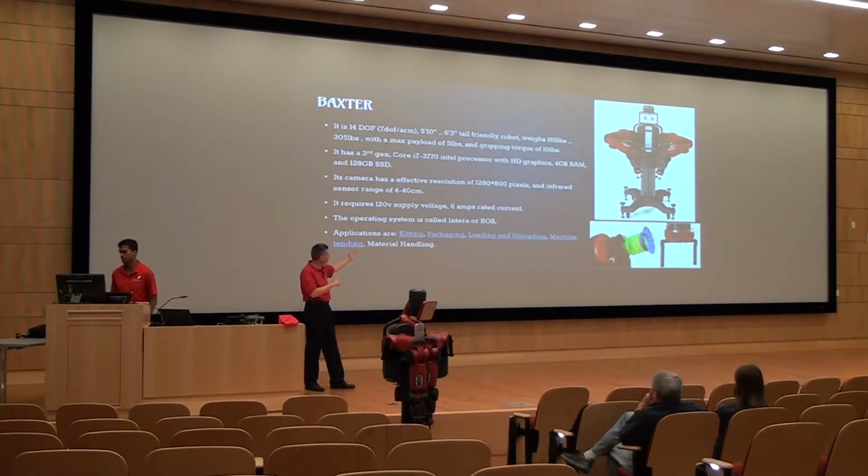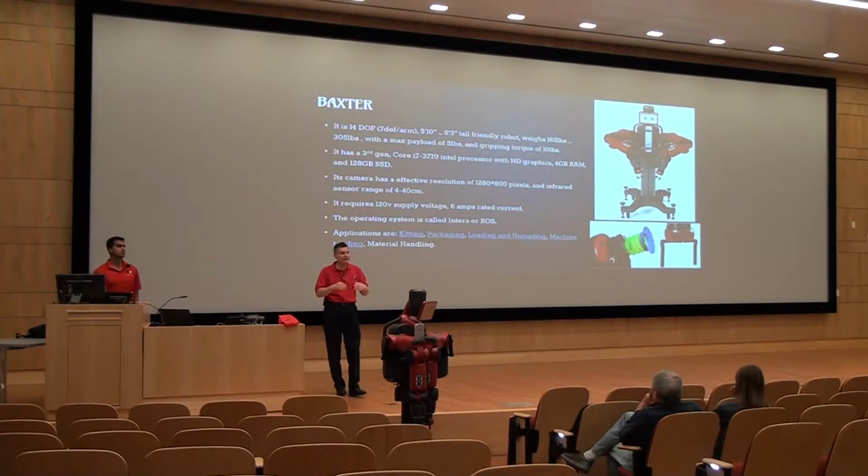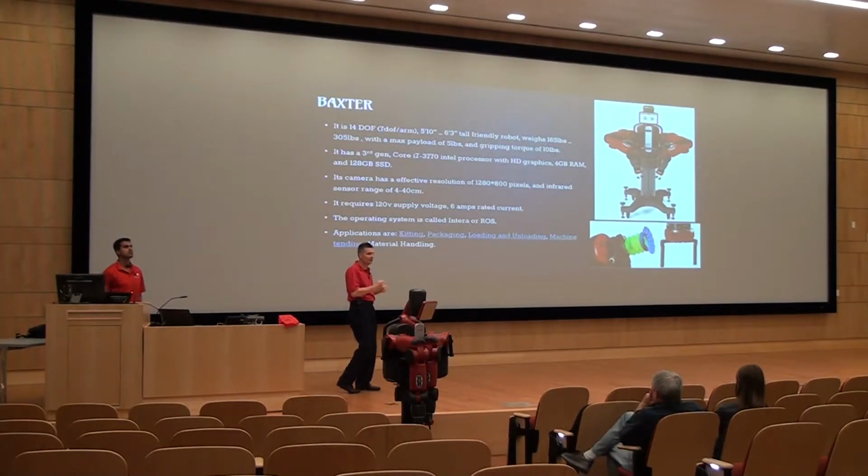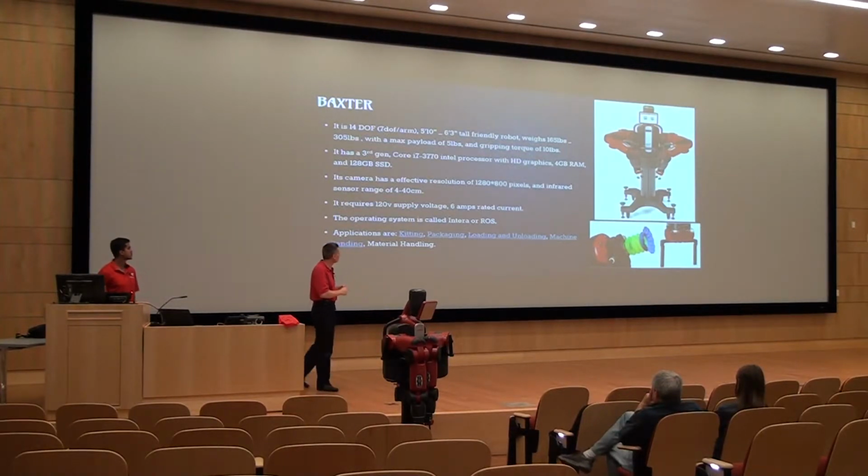In this case, with the Baxter, we have to be careful what we can do with that robot. It is not a high payload robot, it is not a fast robot, it is not a very highly repeatable robot, as we've come to find out. But it can be used in a lot of instances like kitting and packaging, machine tending operations, and if you were to scour the web, that's where you would find these robots in these types of applications.